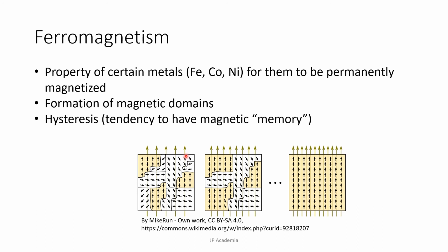If an external applied magnetic field, on the other hand, is present, as shown in the drawing and going upward, alignment in the domains can be observed. Thus, application of small external fields moves the walls to form larger domains, and higher external fields rearrange these domains in the same direction and increase the net magnetization as shown.